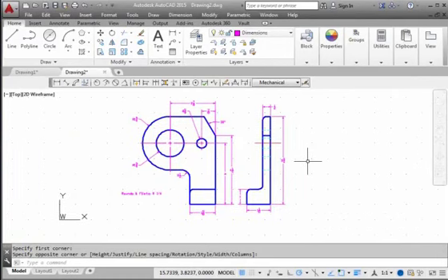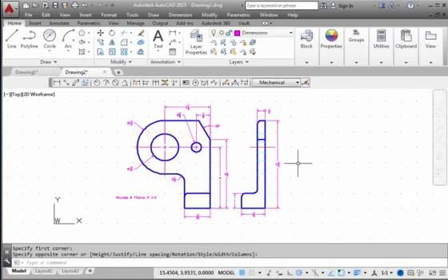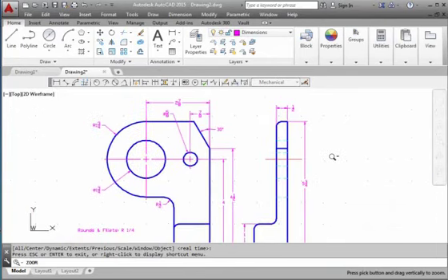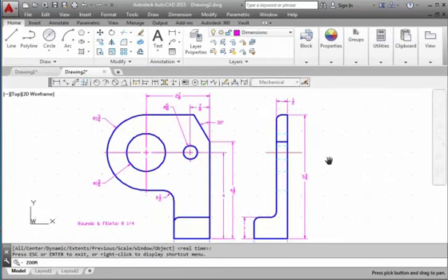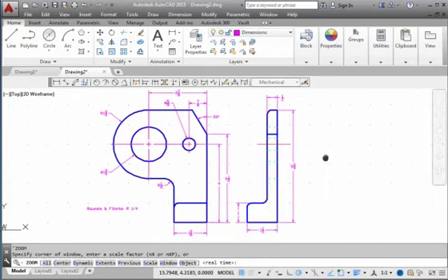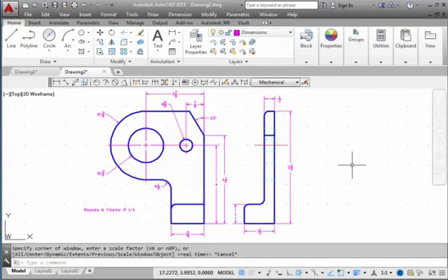In AutoCAD, we can also add special characters in our general notes. For example, if we need a diameter symbol, we can type in %%C, and AutoCAD will convert the code to a diameter symbol. If we need a degree symbol, we use the special code %%D. For the plus/minus symbol, we type in %%P. With the multi-line text editor, these special symbols can also be selected through the control toolbar. We have completed the tutorial for Chapter 6.